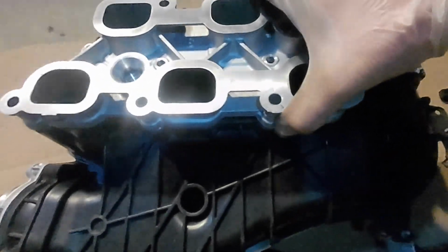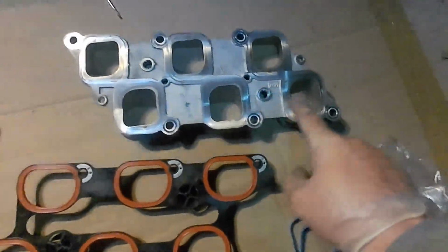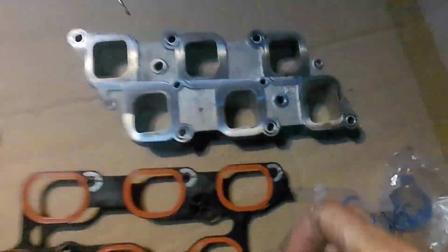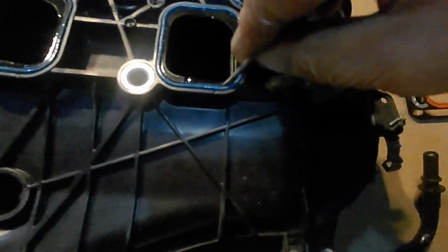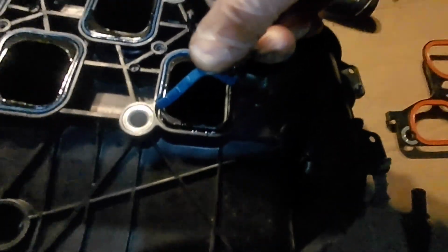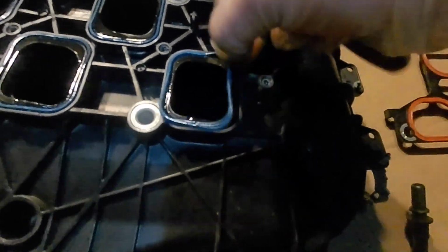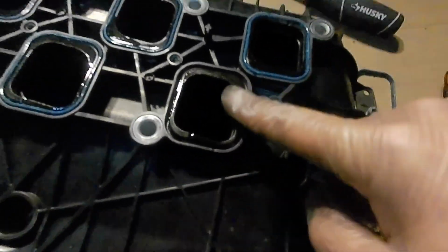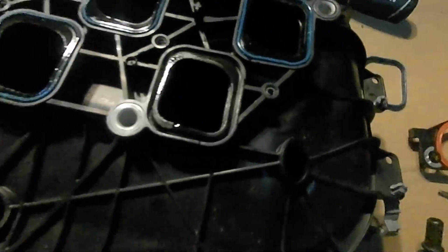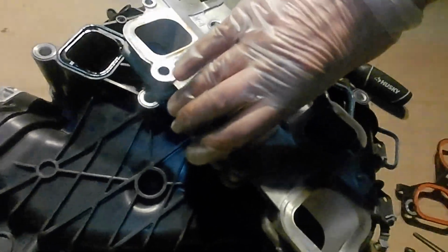Then you will probably be able to manually remove this top piece. Get it cleaned all around the gasket areas, and then these are the gaskets that need to be replaced. So I'm going to get them out. They're kind of stuck because of the heat, but there you go. You get it out. It's kind of melted in there. Then we'll do some cleaning with a rag and parts cleaner, and then we will be able to place the new gaskets in there, and put this part back on top.